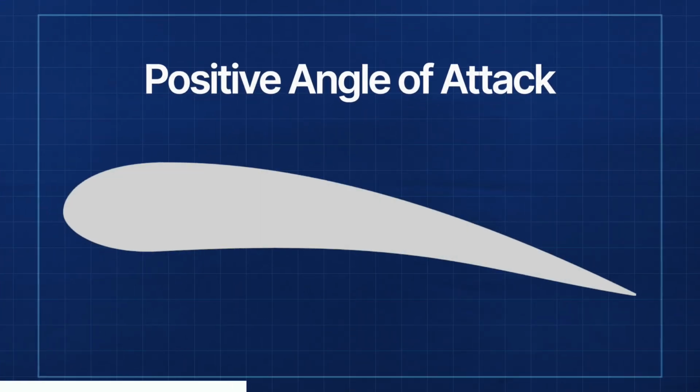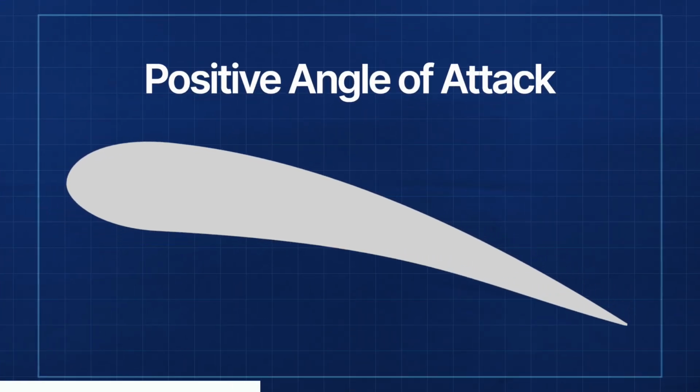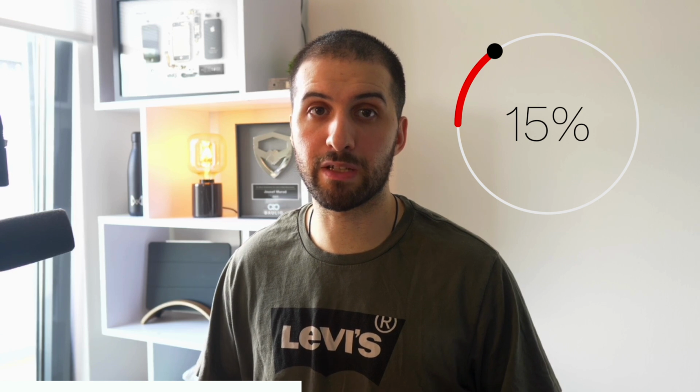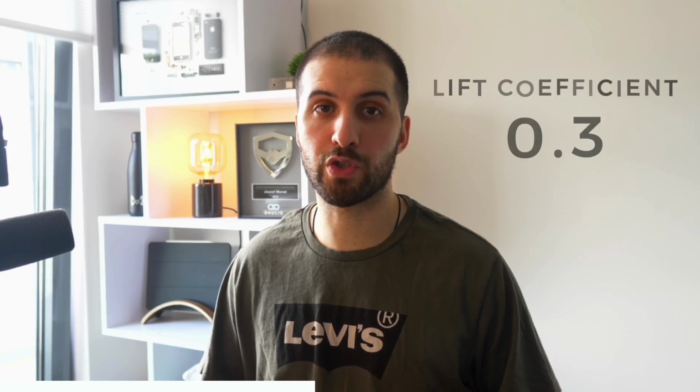Development efforts were undertaken by NACA in the 1930s to develop airfoils capable of longer runs of laminar flow. There are a couple of standout features that make the 6215 profile a great choice for our simulation today. Firstly, it allows for a positive angle of attack due to its streamlined design, resulting in less turbulence and greater steadiness. Second, it boasts a thickness of 15% of the chord length and a design lift coefficient of 0.3, making it a versatile choice for a wide range of applications.